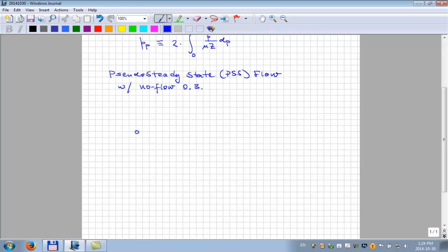basically we've got a wellbore. I'll try to sketch it here without too much thickness out to here. This is RE. This is from the center of the well out to there, and then this distance here is RW, wellbore radius, and we've got no flow at the outer boundary. I'm just going to take, it's 360 degrees around, I'm just going to give you a section of about 30 degrees. It's actually going all the way around, the whole way if it's draining a total volume.